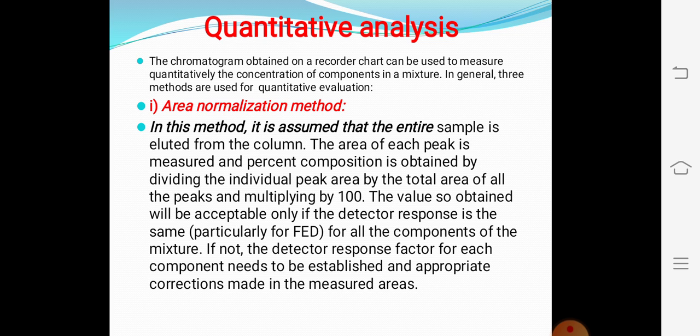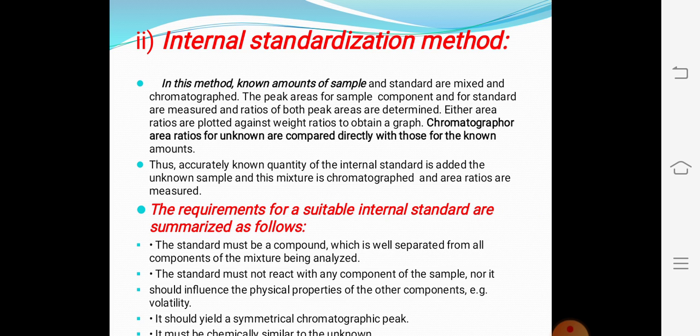The values obtained will be acceptable only if the detector response is the same for all the components of the mixture. If not, the detector response factors for each component need to be established and appropriate correction made in the measured areas. Second is the internal standardization method.